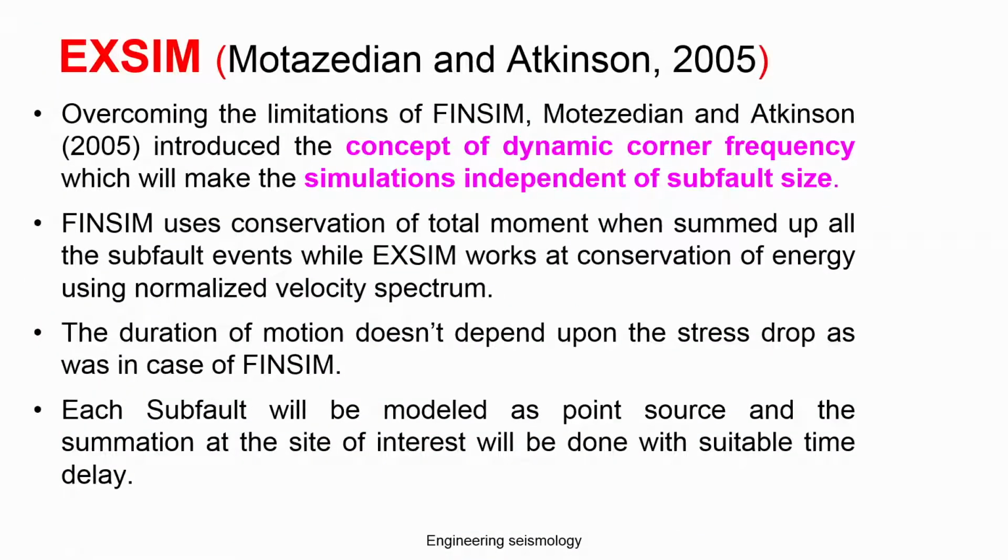So the EXSIM, Motazedian and Atkinson 2004. In order to overcome the limitations in the FINSIM model, Motazedian and Atkinson introduced the concept of dynamic corner frequency. That means the corner frequency keeps on changing, which makes the simulation independent of the subfault size. So now this model overcomes the subfault size problem.